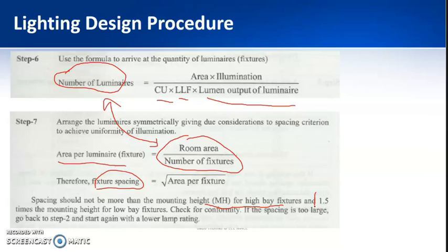And if the spacing is too large, then you need to go back to the first step, and then you need to change the wattage of the luminaire so that the luminaire output is less, and then you can do the calculations.